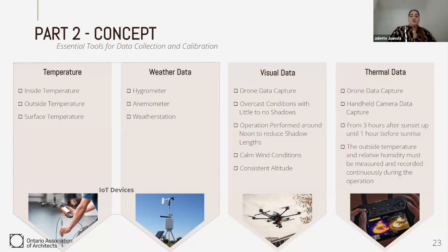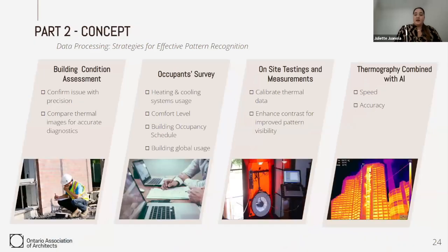And the thermal data capture is really specific. If you want to have the highest quality data, this operation needs to be conducted at night to just get rid of the solar loads. So basically from 3 hours after sunset up until 1 hour before sunrise is really the best time to perform this type of operation. So once this data has been collected, it is time to process it.